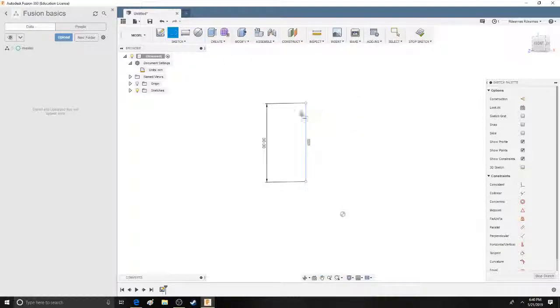We're going to be attaching another one up here and getting it around the same size. Let's not do this one exact. So what you just did there, and of course, check mark if you've completed it, you're just clicking in 2 separate positions and then connecting them. Of course, you can move back to the select tool, which allows you to check out certain aspects of it, as well as edit some of the things in the sketch palette. But now we're just going to be creating another one. So you're just clicking in one position and dragging to another.